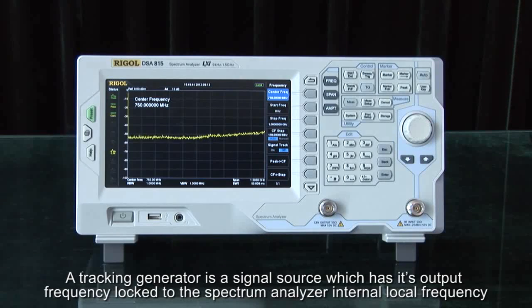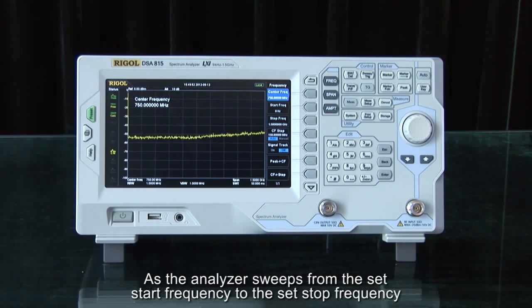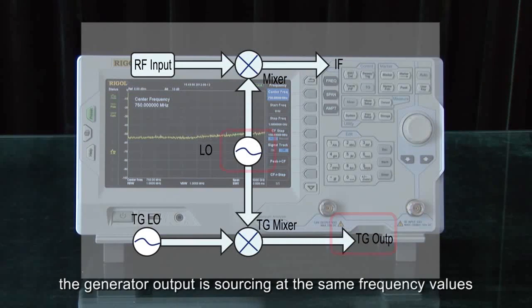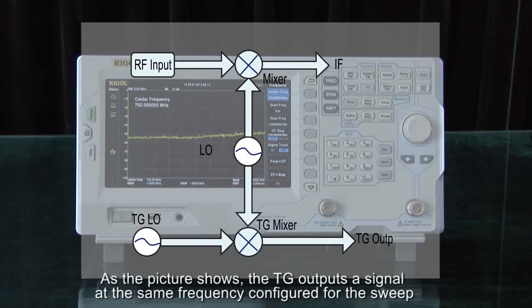A tracking generator is a signal source which has its output frequency locked to the spectrum analyzer internal local frequency. As the analyzer sweeps from the set start frequency to the set stop frequency, the generator output is sourcing at the same frequency values. It tracks the input sweep. As the picture shows, the tracking generator outputs a signal at the same frequency configured for the sweep.